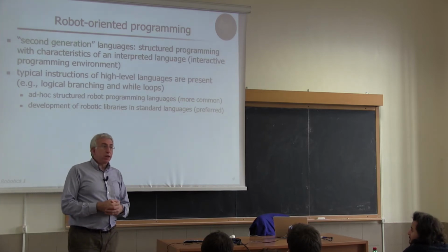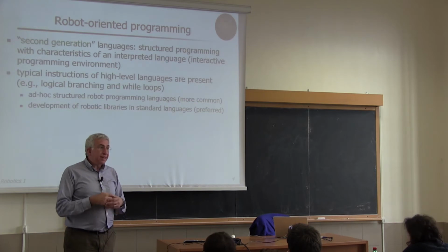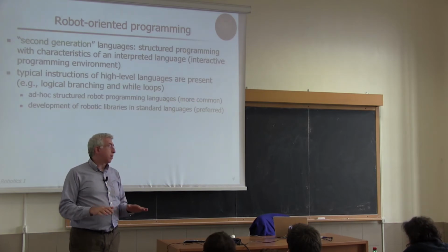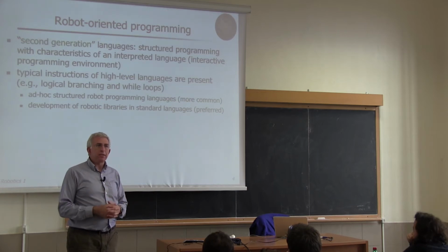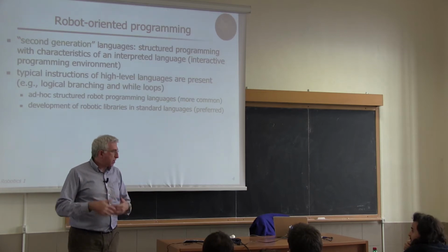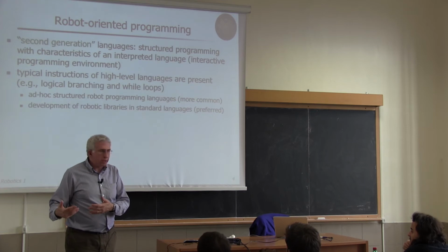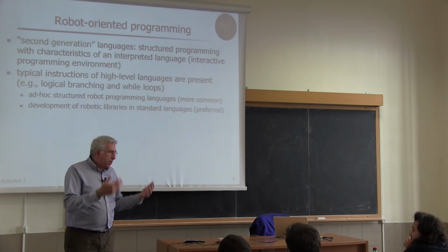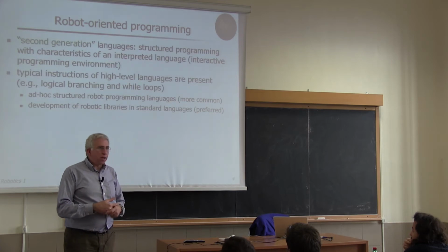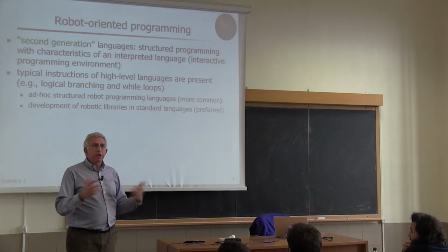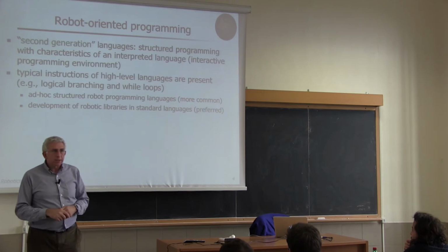If you're using an industrial robot, you should always leave some low-level instruction that are run in parallel to what you're asking to the robot, like checking that the motors are correctly operating, and in general, safety checking and coordination of reading and writing on input and output ports.